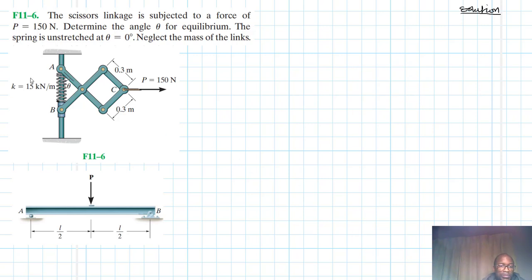So we have this beam here, I just want to demonstrate on this simply supported beam and apply the principle of virtual work. So what we are going to do is we are going to release one of the supports, okay, and where you do the release, it really doesn't matter, but for us, we release it at A and leave B fixed the way it is, hinged here. And we are going to apply a virtual rotational displacement at B, delta theta. So let's apply a rotational at this point here.